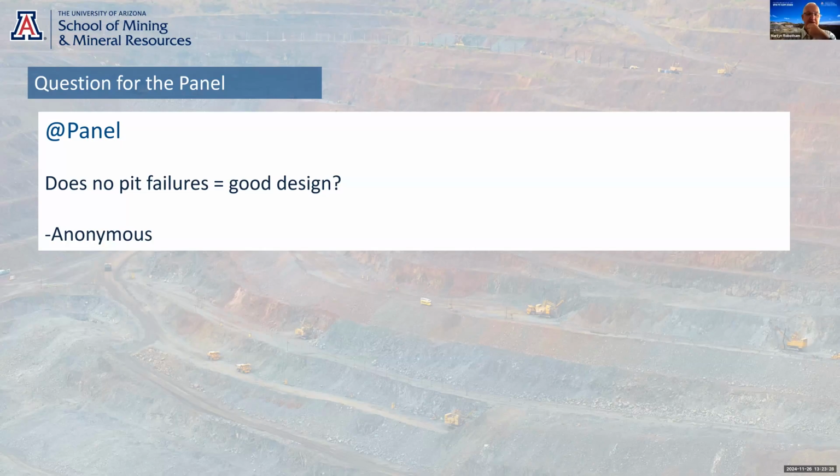Yeah, I'd agree, Scott. I'm happier with lower figures than that. 5%, 1 in 20 chance of a global instability in my mine? There's a lot of uncomfortable people looking around it then. And again, maybe a little controversial, but I'm not the biggest fan in the world of probabilistic approaches to large, complex geological slope failures. Much as factor of safety isn't perfect either, I think it's good to run multiple methods to have a look at, to try and evaluate the risk, and as Mark says, what the impact to your business could be.